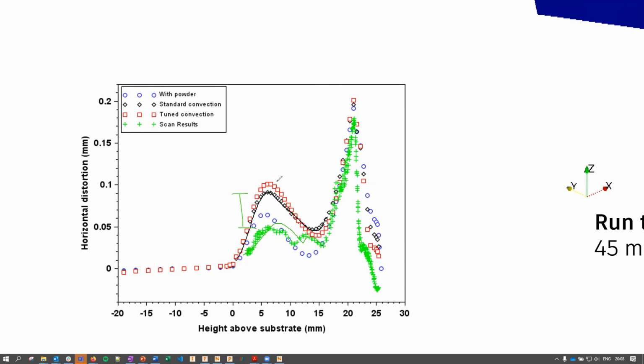As I explained, we assume that heat that is not used for doing any work simply dissipates out of the part into the surrounding air. However, once we started to model in the powder and model in the conduction, we saw that we were getting results which were a lot closer to what was happening in real life, which is what you see over here.